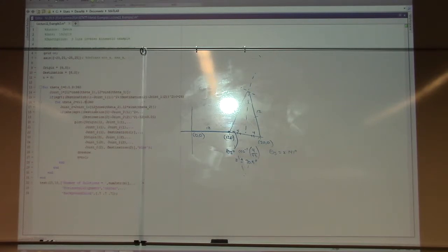In fact, with a step resolution of 1.8 degrees, you need 200 steps to complete a full revolution. And that's part of the reason why engineers back in the day developed stepper motors with a 1.8 degree step resolution, because it was an integer multiplier of the 360 degrees for the rotation.